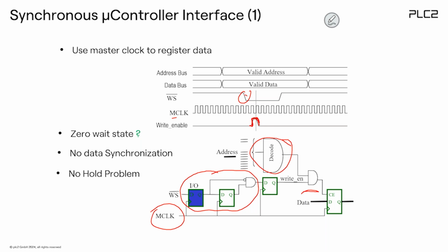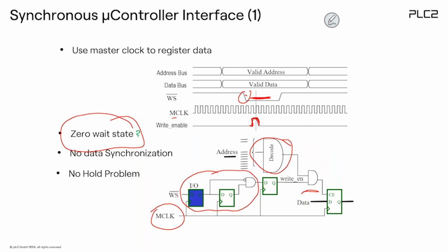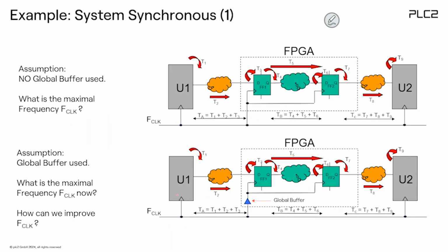It's very, very nice, it works, but what's the disadvantage here? The disadvantage is usually it's not a zero wait state application, because we will need a certain width of the write strobe. If I go back to this one, in this case, it is a zero wait state application because we are taking the data immediately and don't have to wait. So it's your choice, whatever you like. Okay. So these are the applications here. But again,